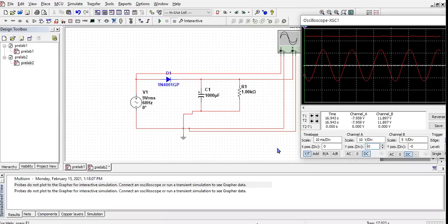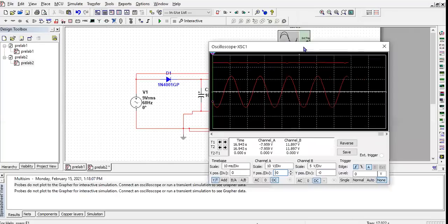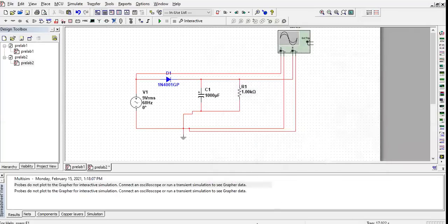But when you multiply 9 by 1.414, it will give us 10.269. As I told you, there are some errors because of the tracing. You need to set them as well as possible. So this point is clear: how you can get the value of the DC level, how you can get the value of one peak, and how you can get the value of two peaks altogether. Yes, doctor. Clear? Okay, good.